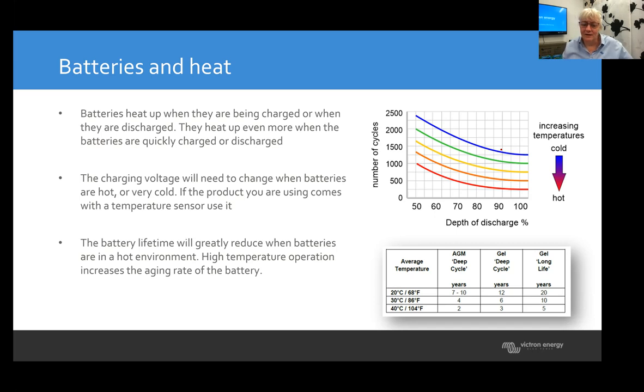So if you're in the middle of the Australian desert and you have a little shed where there's a battery sitting in there because you've got a small solar panel, maybe in a mining application or an off-grid station, a farm, if you have your battery sitting there at 40, 50 degrees Celsius, that's not good for the batteries. And you might not get, AGM cycle. Yeah, you have to pick the right battery for the job. So if you go in the Australian desert, you might get even less than that if your shed gets 60 degrees Celsius. So it becomes important to keep the batteries cool.